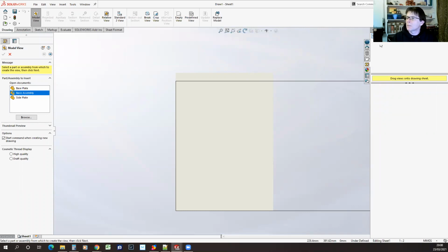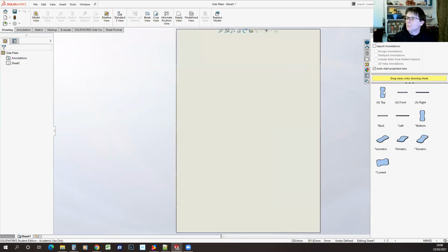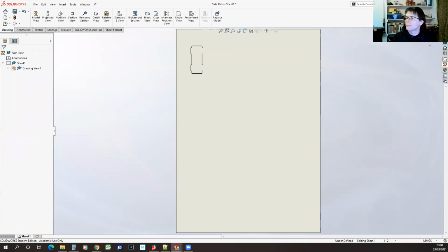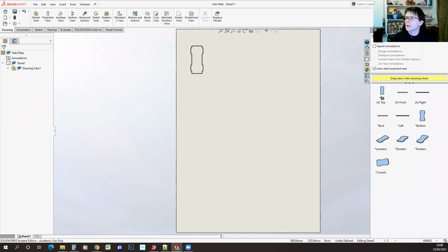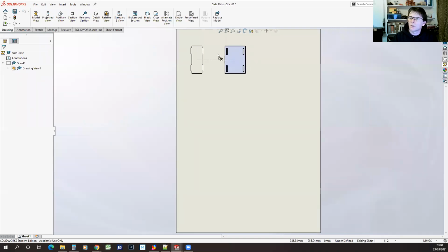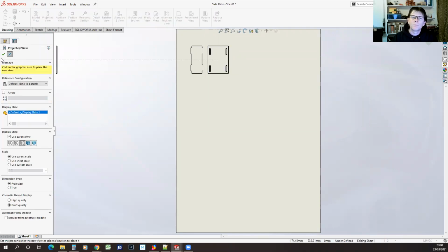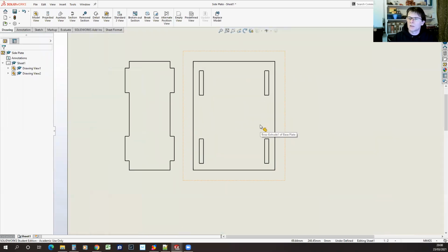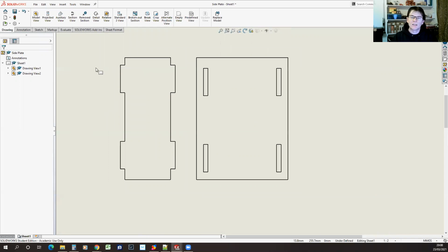And then over here on the parts menu, I can pick one of my parts, drag in the top view of that part, and click the tick, and then I can select my other part. The parts appear here if they're open, if the documents are actually open in SolidWorks right now. If they're not, then you can use the ... menu to go and browse for files on disk. So we'll also grab the base plate and drag one of them in. And there we've got essentially the drawing that I want to put into the laser cutter to laser cut those two parts out.